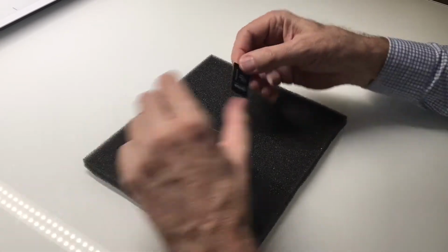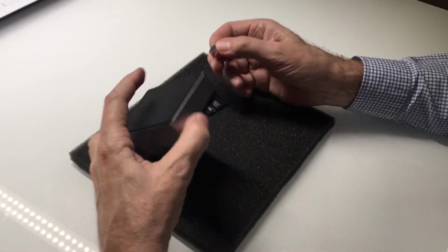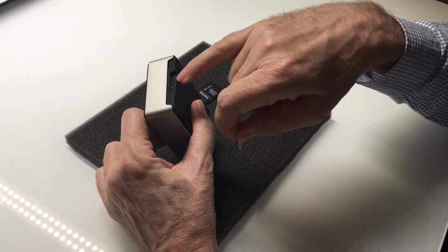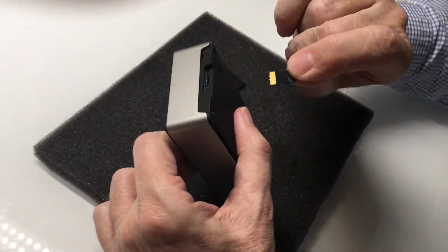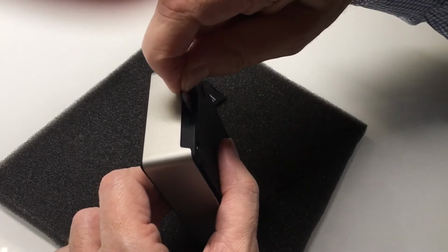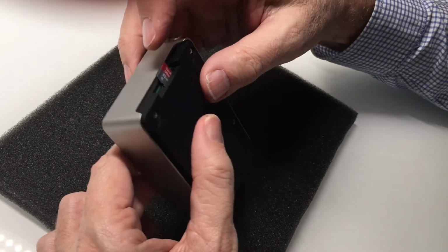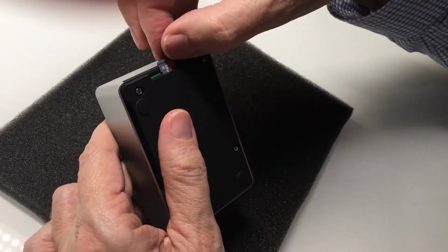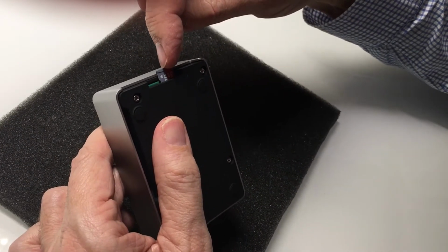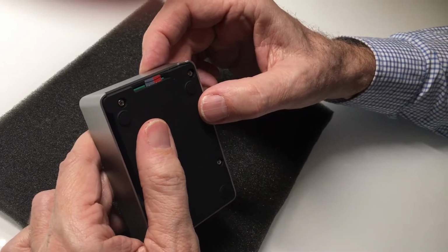Our SD card is programmed now. We take it out and we have to insert it in the Raspberry Pi. There's a little slot here and we have to put in the card that way. If we do it in the opposite direction, this will ruin your Raspberry Pi. So be careful, that way, in there, with a little pressing, and that's the way it should look.